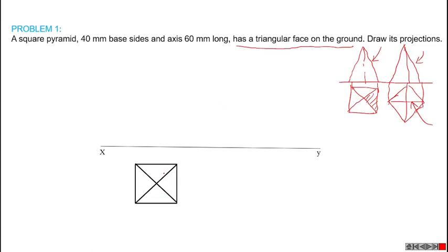In order to represent the pyramid, we must represent the slant height. Otherwise, that figure will represent a prism. Without the slant height, we can represent a square like this, but that figure is the actual representation of a square prism. In the case of a square pyramid, or any pyramid, there must be slant heights.